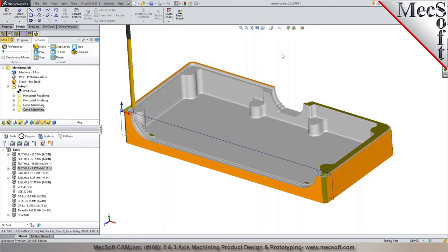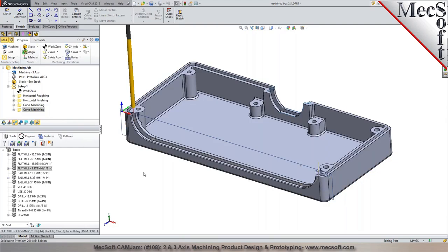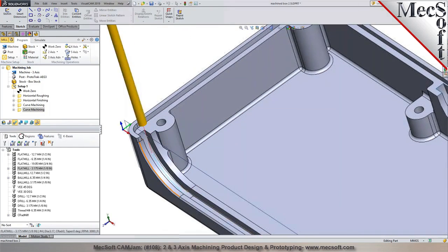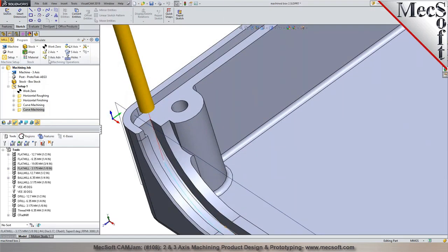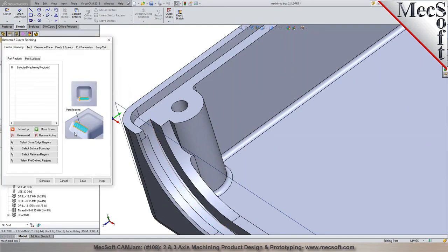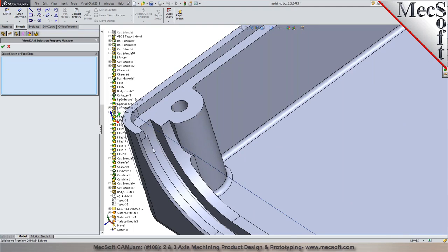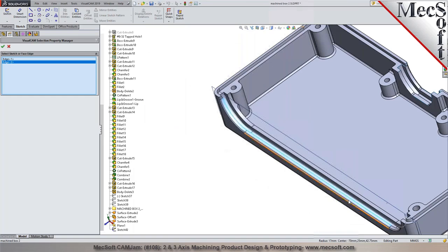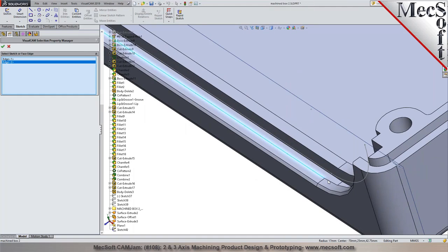Yep. Yeah, is there any other way besides going in and creating planes and sketches? Like, is there a way that you can use a 3D toolpath and just select all those surfaces so that it kind of localizes? We could do what's called between curve machining in here. So I could do a 3-axis between 2 curves machining. And I can select a set of 2 curves. You can use face edge selections in here.